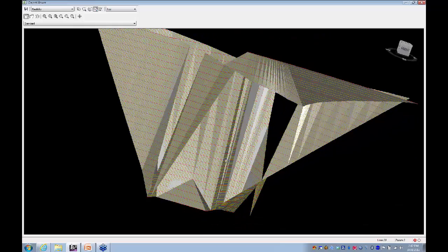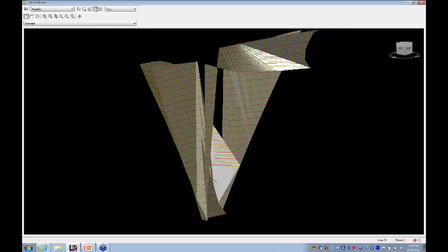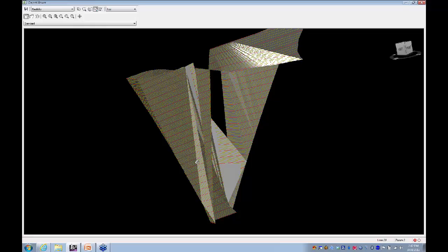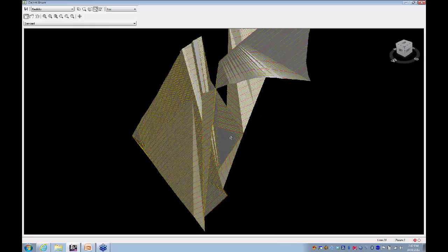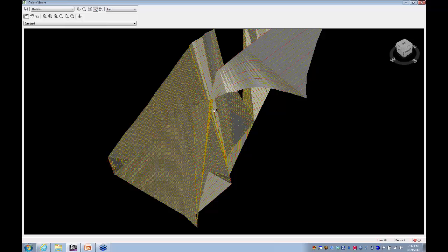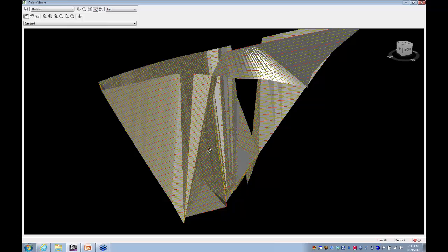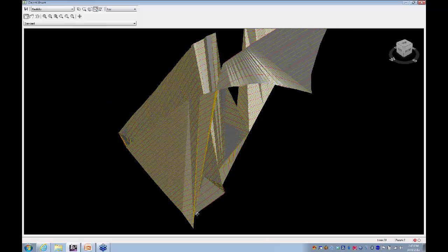If you ever see that, it's a really good indication that you've got either an alignment or perhaps another feature line at a different level, or an unintended level, from all the others which were working to put this dam together. So this produces the Sawtooth Effect. And really what it is, the alignment is running down at the bottom, well, it's actually at zero elevation, because an alignment has no elevation. Or it may be a feature line at 50 meters elevation, which is different from the crest of the dam. So the grading is running between the two, because it doesn't know which level to use.